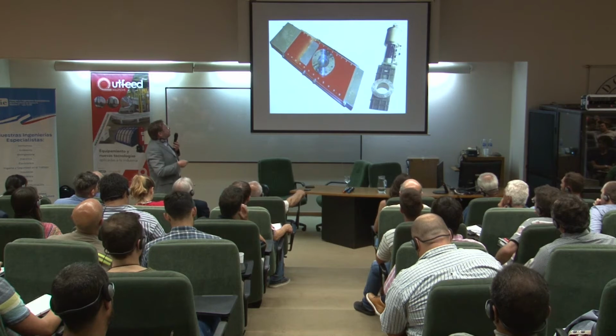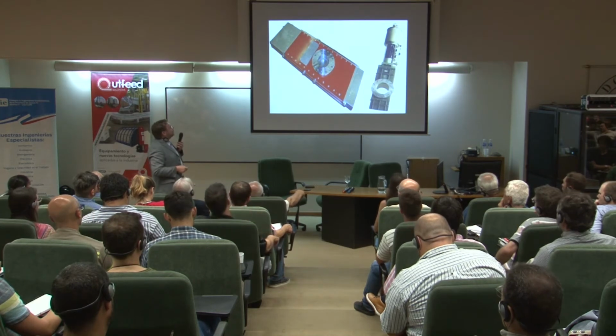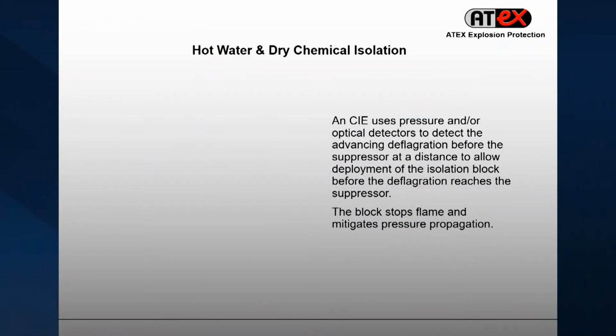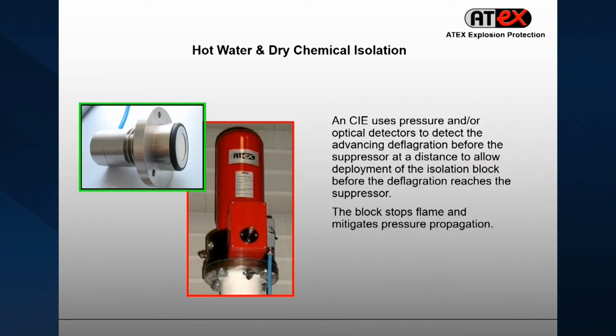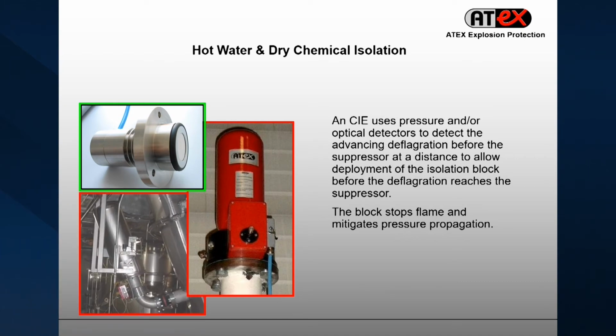Just a few pictures of typical active explosion isolators, and of course also hot water or dry chemical. The flame extinguishers can be used for isolating an explosion, where you use pressure detection and then either a bottle with a powder or hot water.